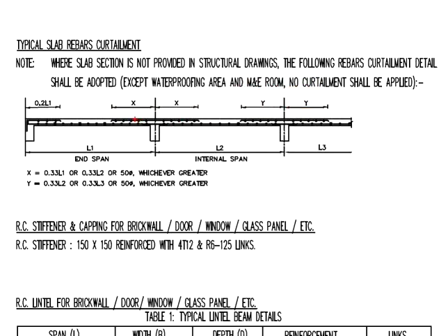Now the question here is, how much is this width? To determine the length here, you need to first get 3 numbers. We are talking about 1/3 of this span, which is 0.33 times the length of the span, and then 1/3 of this span, which is 0.33 L2, and also 50 times the diameter size. Based on the 3 values obtained, you use the largest value.